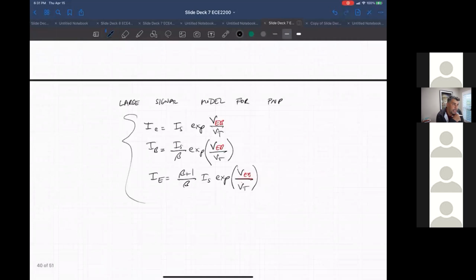Depending on how far we get into chapter 5, we might not see PNPs again in the circuits. Depends. PNPs typically get used as ways to bias NPNs. When you don't, you can use resistors. There's some benefit to using transistors to bias up instead of resistors. So let me see if I can pull it up to give you guys an idea.